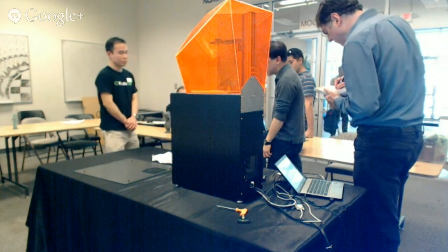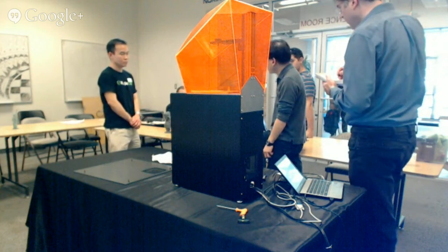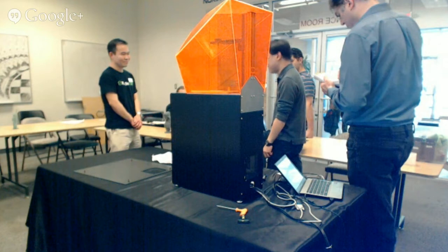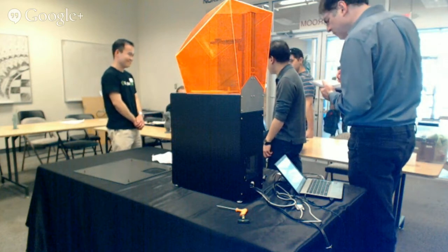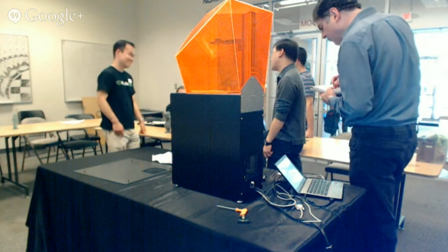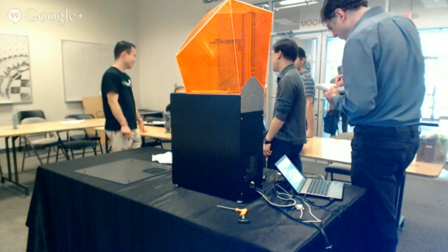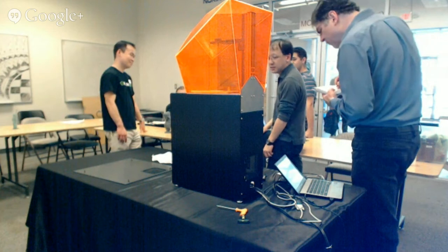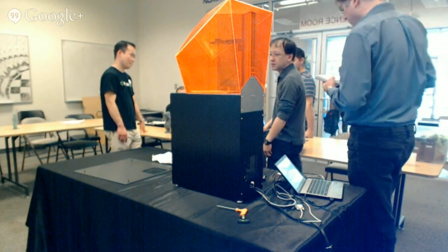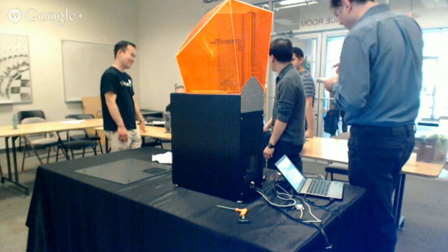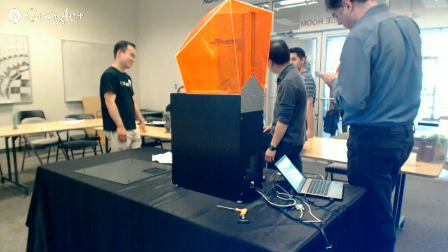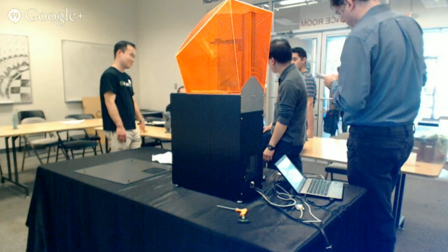They also have a DLP 3D printer. The filament one will work for yours, like the spiral staircase, but that's really hard. Even if you print it, FDM is bad at really fine details. The filament 3D printers are cheap, but they're bad at small, fine details. This one's really useless, and it's also bad at unsupported areas. For a camera it's not really a big deal, they seem to work okay.